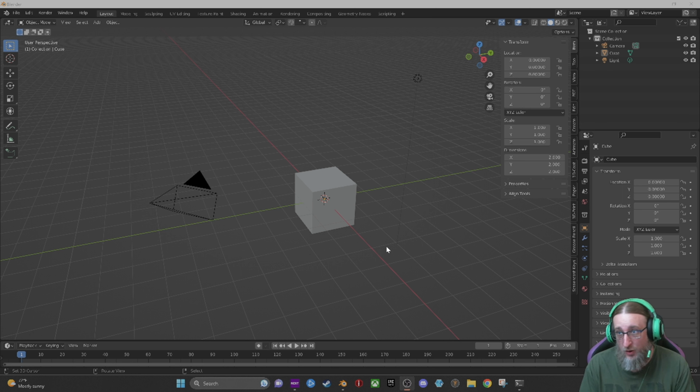All right, now after that, all we're going to do is apply those two things we just did. So first, we're going to apply the subdivision surface. Always apply the modifiers in the order that you have them stacked, because they matter. For instance, if I take my subdivision surface and move it below my displace, I lose all of those subdivisions before the displace. So it's only using the initial subdivisions on that, if you see what I mean. So you can just grab it and drag it up and switch them back over, and then you'll get the image that you want.